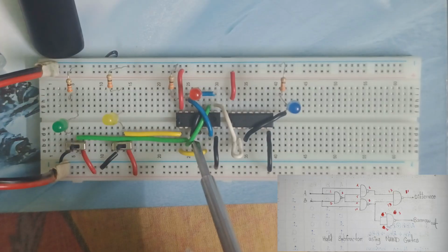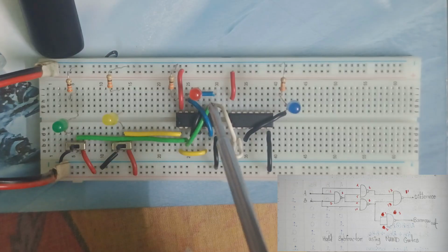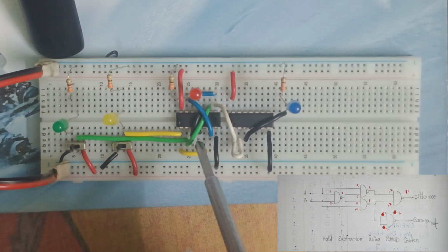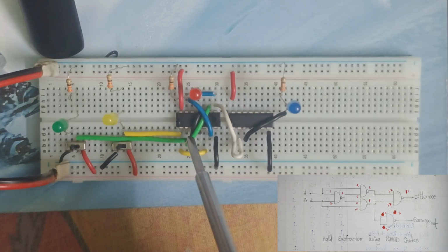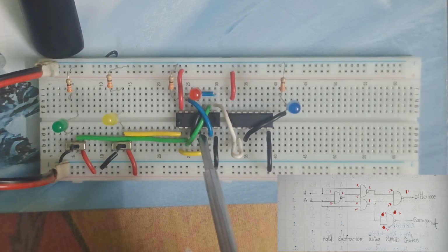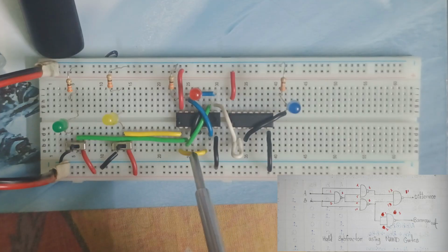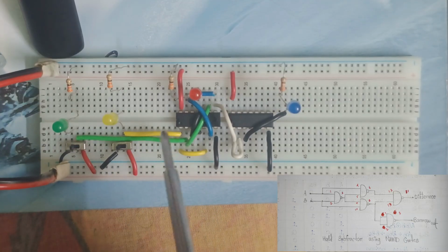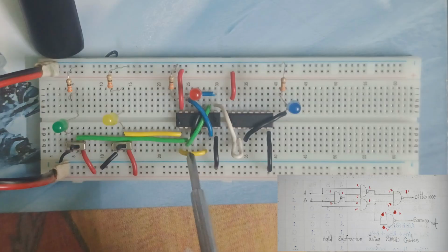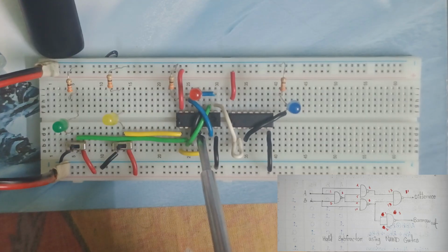So that output is getting spread between the two inputs of our different NAND gates in the same IC. And the NAND gate needs two inputs. The first input is connected to pin number 3, and the second input of this second NAND gate of the IC is connected to this yellow wire which is connected to pin number 1, or we can say that it is connected to signal 1. This is our signal 1. So it is doing the NAND operation between signal 1 and the output from pin number 3.